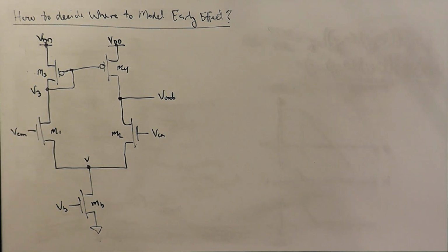Okay, so for the differential mode gain calculation for this circuit, there were basically two phases of the calculation by node fixing. One was the transconductance gain of the circuit under the conditions of the output voltages being held fixed by an ideal voltage source. Okay, so during that phase, the output being held fixed by an ideal voltage source is part of the deal.